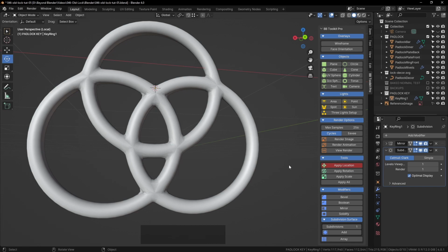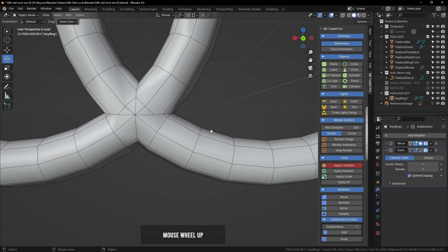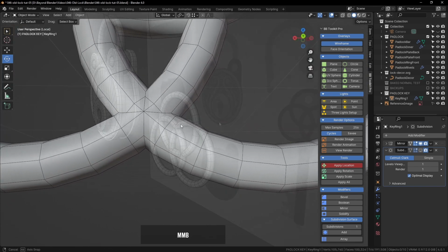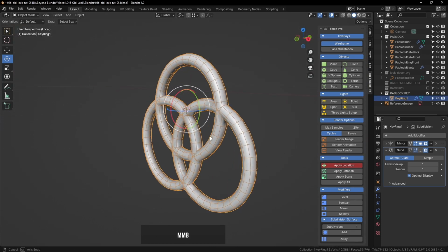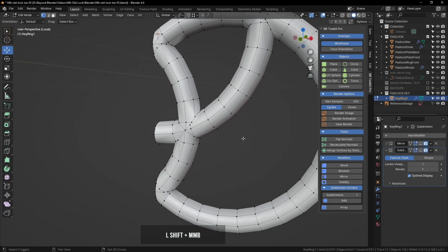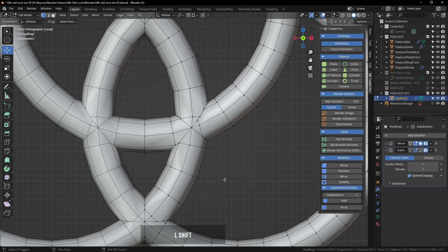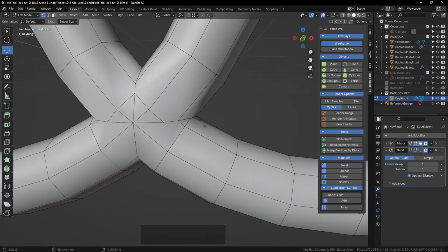Let's turn that down to 1 level, and disable the subdivision modifier for now. Let's turn wireframe overlay on. That will really help us see what's going on and where the issues are. I'm going to isolate that with the question mark / key on the keyboard. Let's turn off all the modifiers as we tidy this up, apart from the mirror.